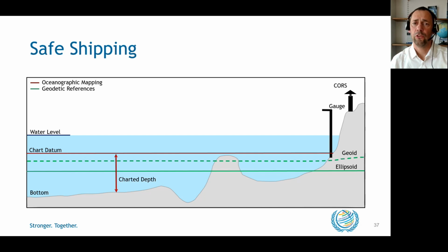Additionally, we assume we already know the bathymetry, the seabed topography or underwater depth of ocean floors, which is given through oceanic mapping in a chart datum. As the water level is not constant over time, we introduce also a mean sea level, the average water level.